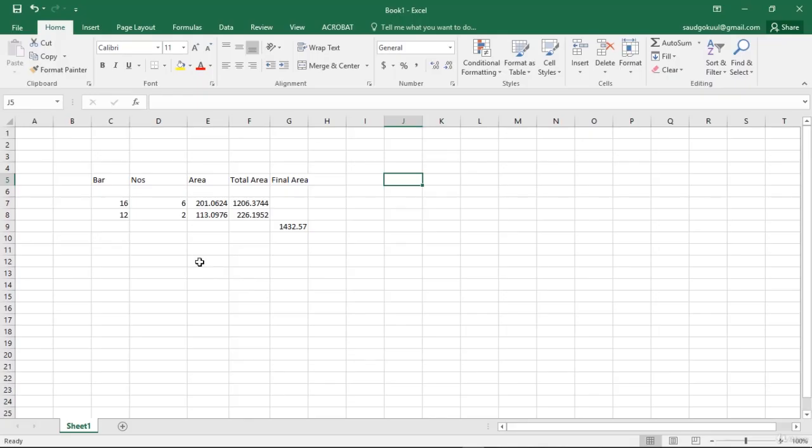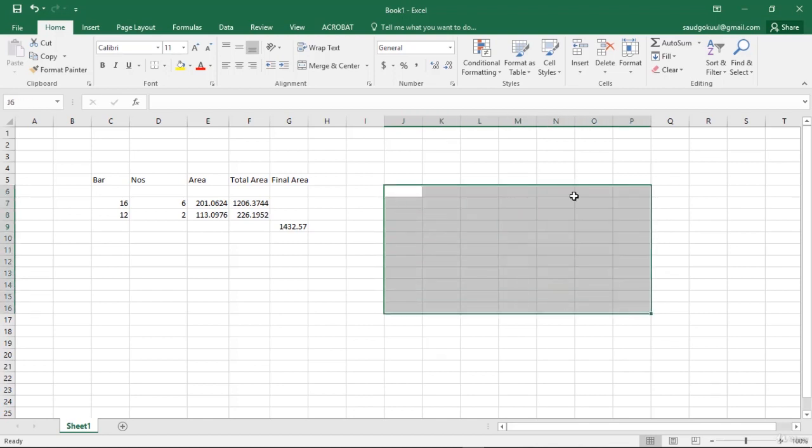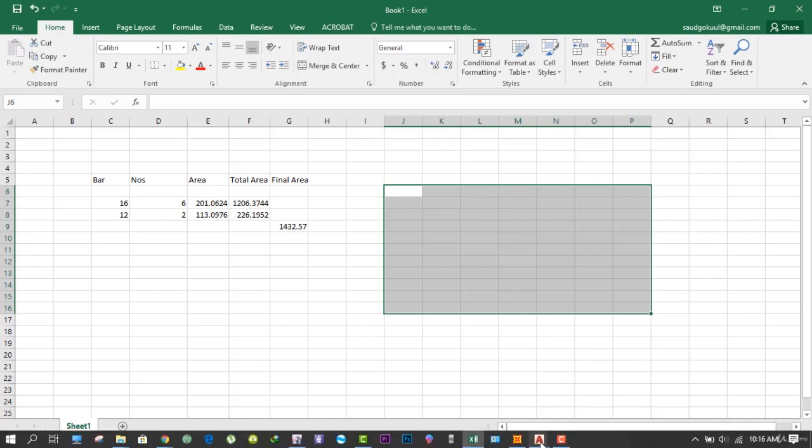Okay, what you have to keep in mind is that you have to make combinations of these bars so that you get the reinforcement value that is equal to or greater than the required value. Okay, so this is how you detail your column, and while detailing you have to make sure that while lapping the bars from lower floor to the upper floor, the lower floor bar is of higher size than that of the upper floor. Okay, after detailing you have to draw these detailing diagrams.